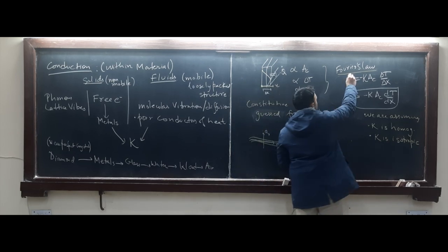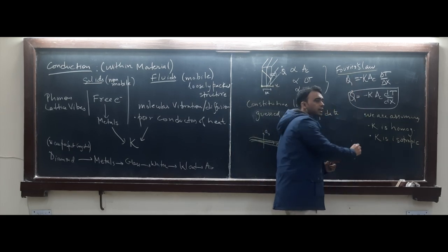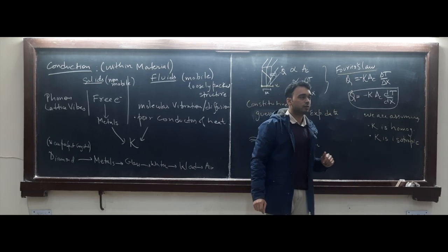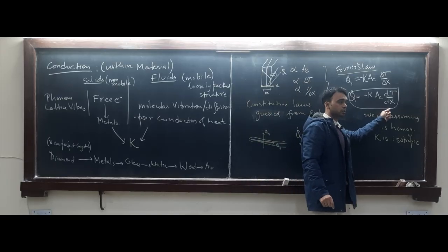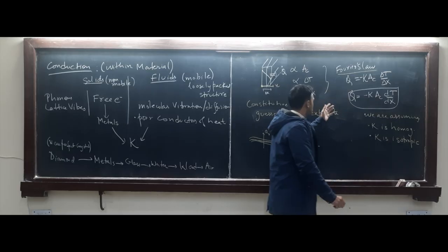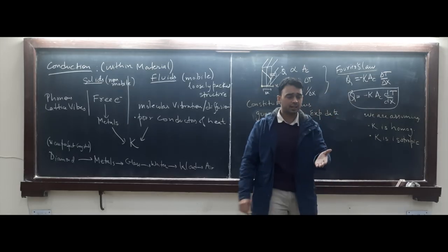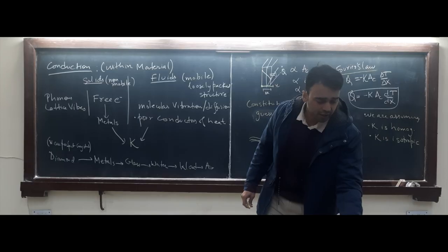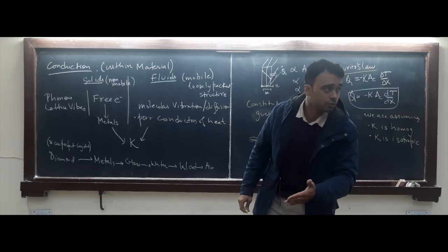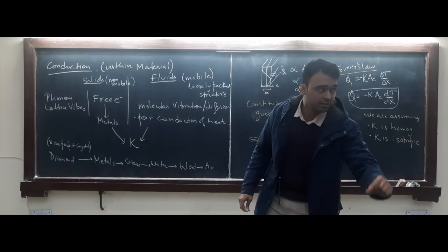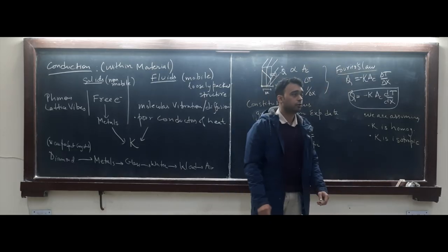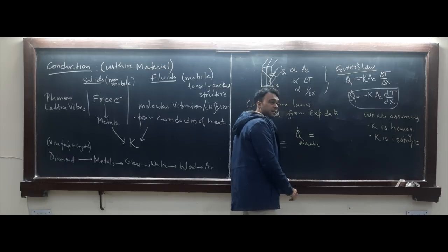We did not write it here because it's a flow, it has a direction. It has the direction of X. Fourier's law is for some simple materials like this engineering wood where everything is homogeneous, everything is isotropic. So you perform your experiments here or here, given the same delta X, you will get the same Q dot. But it will not be the case here.